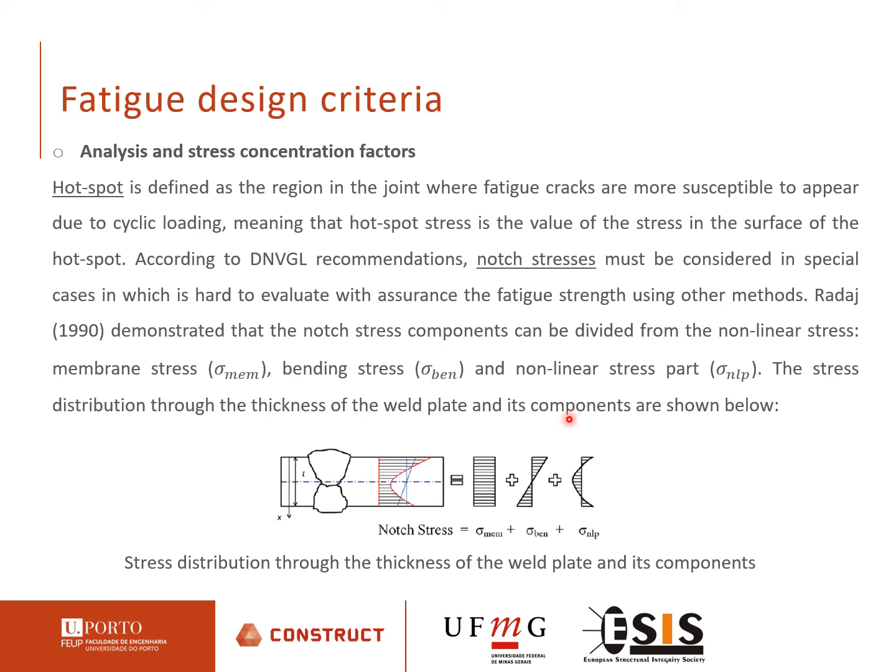According to the DNVGL recommendation, notch stresses must be considered in special cases in which it is hard to evaluate with assurance the fatigue strength using other methods. Radaj demonstrated that the notch stress components can be divided into linear stress, membrane stress, bending stress, and non-linear stress part. The stress distribution through the thickness of the weld plate and its components are shown below.